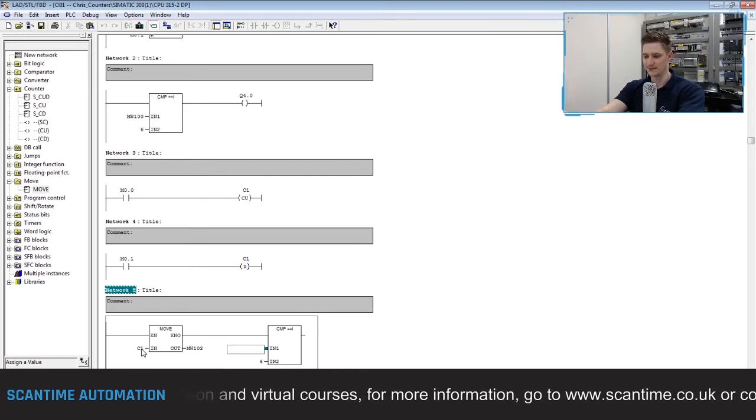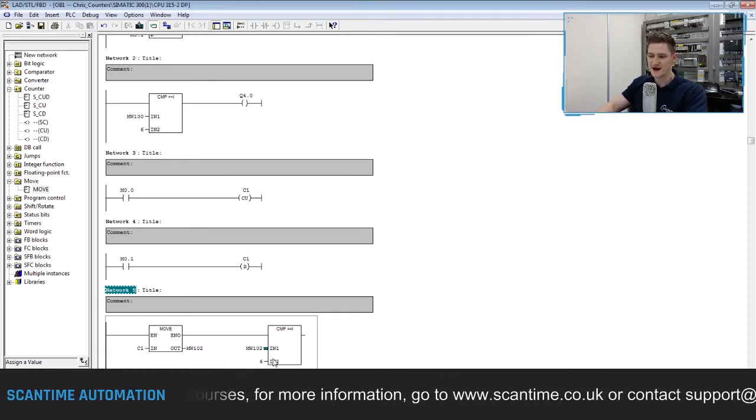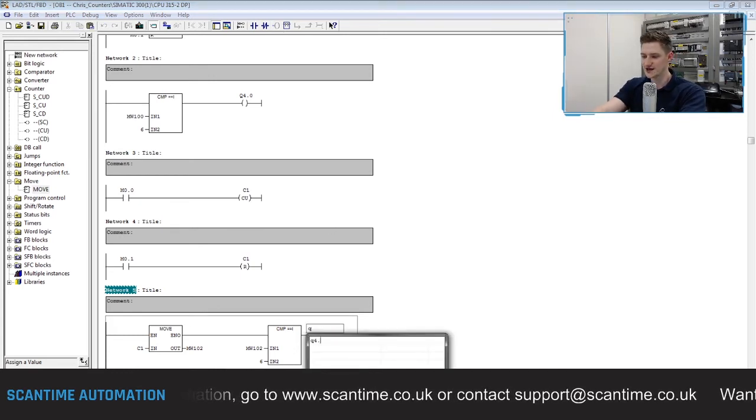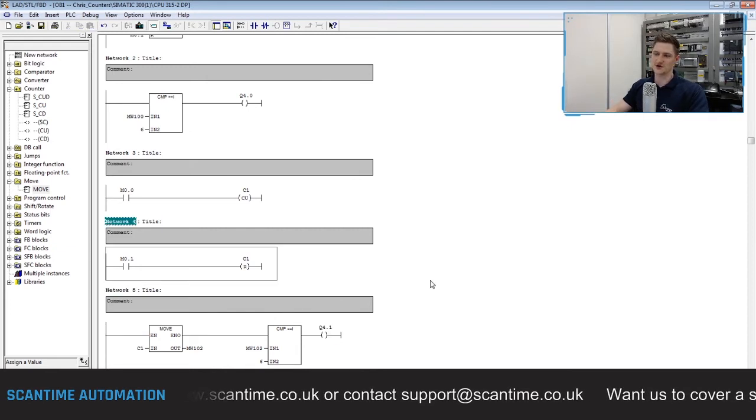Now inside of our comparator, we can write in MW102, compare that with 6, and then when it is equals to 6, turn on our output coil, and we'll use the next one, Q4.1. And there we go, guys.